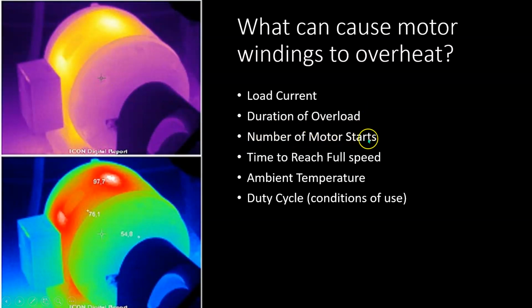Number of motor starts, so starting and stopping motors. When I start the motor, of course we have an inrush of current. That current is going to be quite high, and the higher the current, the more the heat. So if I'm starting it quite often, that continuous inrush of current can heat up my windings and damage them. Then the time to reach full speed. If my motor is starting, it might take a while to actually get up to full speed, and that means it's working really hard to get up to full speed, thus drawing more current and creating more heat.